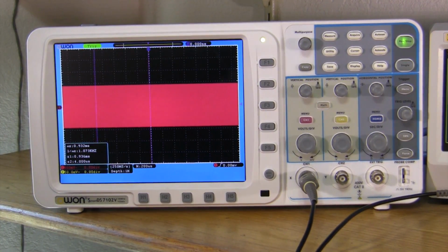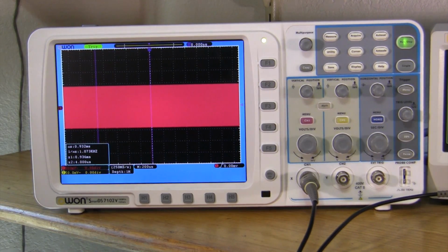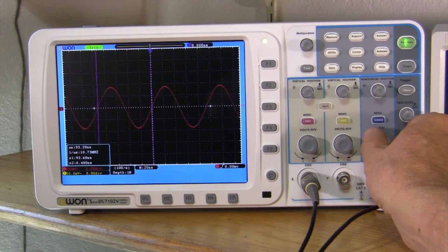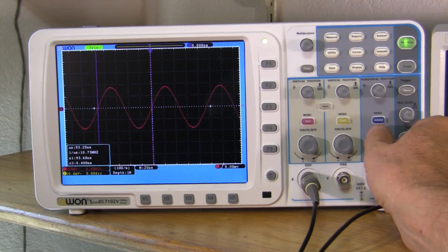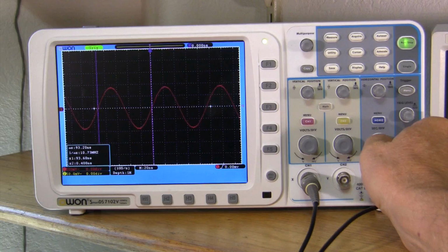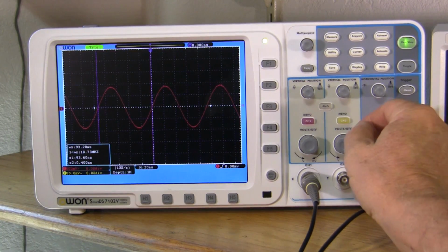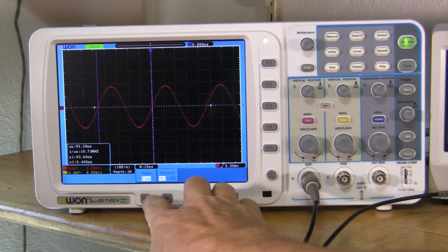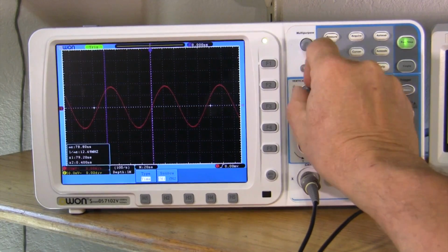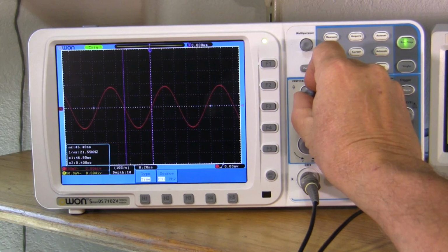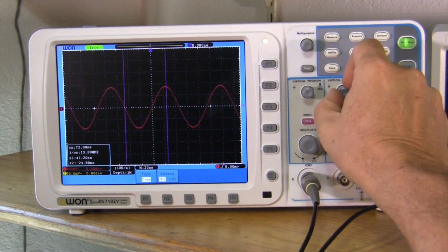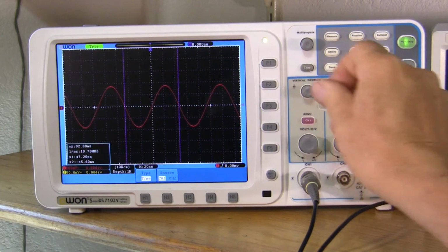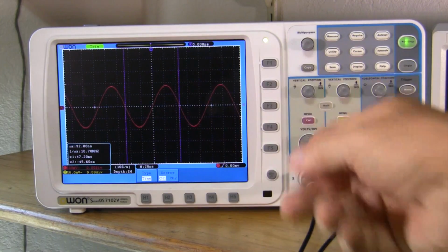as seen by the scope. And if we change the time base here, we'll go through some aliasing here, of course, but then we'll get to something that we can actually measure. There we go. Looks like we have a signal. Let's turn on the cursors. Cursor is set up on time, so if I go right at the crossover point here, which looks to be about there, and use this to go to the crossover point here. As long as you use the same point, it's okay. And it says that we're at 10.78 megahertz, so we're 80 kilohertz off relative to what this thing thinks that frequency is.